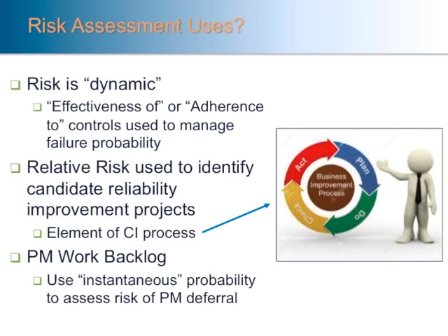Risk can also be a very valuable tool when looking at instantaneous probability methods to decide which PM I have to do right now. I'm not a big advocate of deferring the preventive side of your program. However, there are instances where that must happen. The risk on it, based on an instantaneous probability, is one method that can be used to understand what risk you're willing to be exposed to.